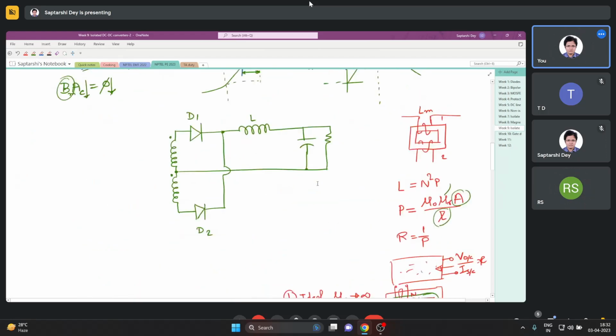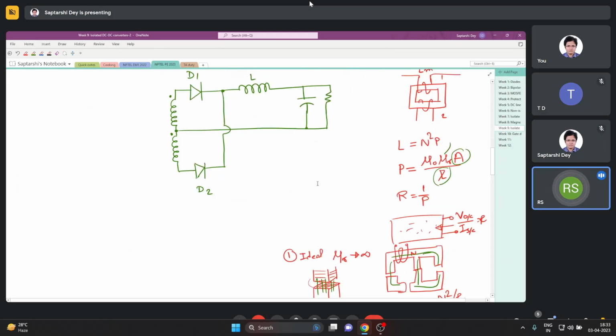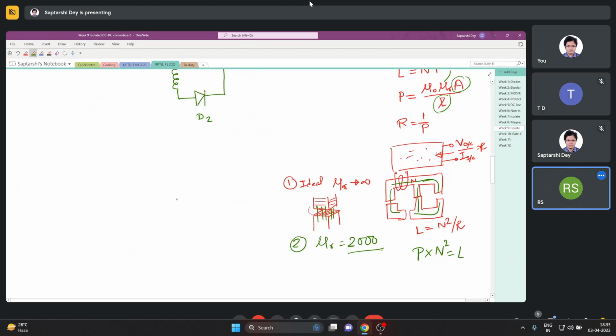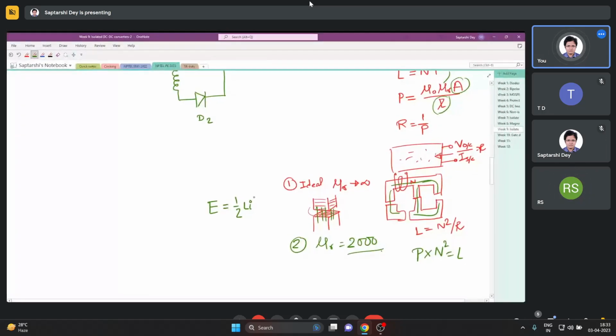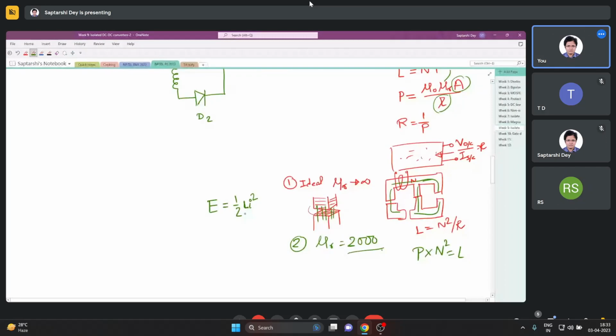But Sir, when we are storing back the energy, suppose to a capacitor on the input side, then it leads to an increase in voltage, because we are transferring energy in the inductor to energy in the capacitor. No, it's being stored in the inductor. It's being stored in the core, and that energy is given by half Li squared. So voltage does not increase. Voltage is stiff anyway from the source side. Current increases.